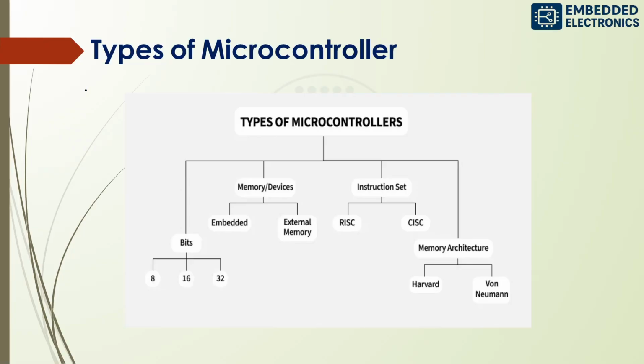But CISC reduces the need for many simpler instructions. So CISC systems shorten execution time by reducing the number of instructions in a program. RISC systems shorten execution time by reducing the clock cycles per instruction. So RISC systems generally offer better execution performance compared to CISC.